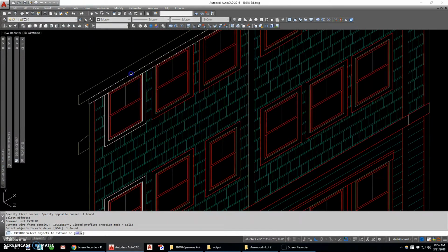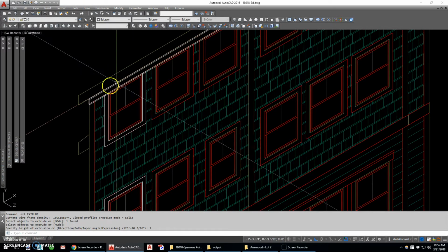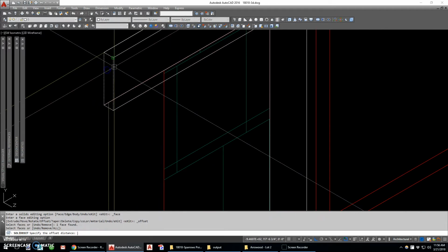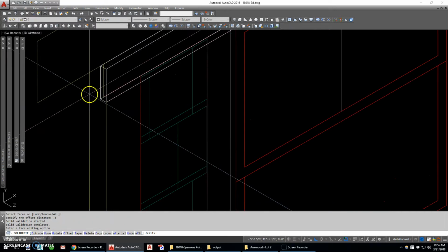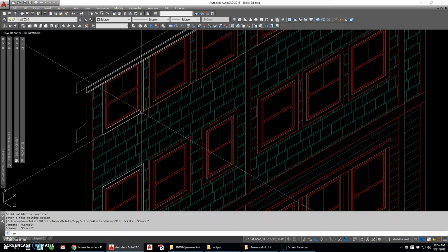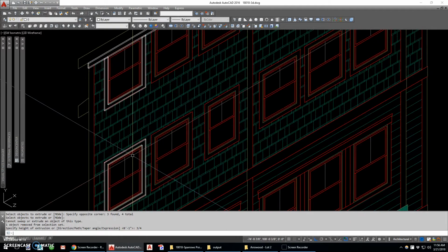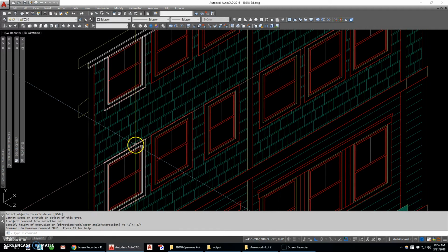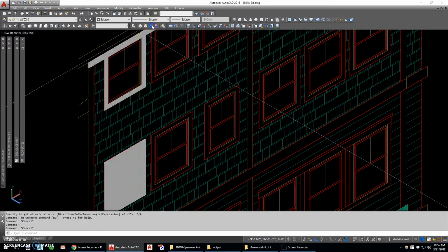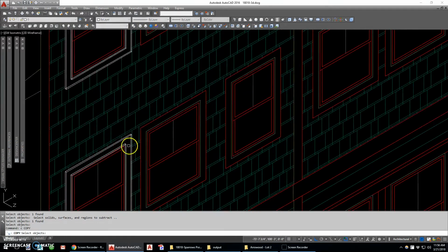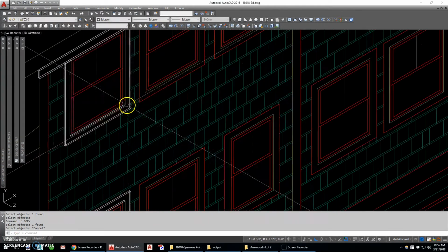So what I'm going to do here is extrude this top piece 1 inch. And while I'm remembering, I'm going to actually offset that face another ½ inch. So it's an inch projected on the side as well. And I'm going to extrude these things 3/4 inch. I've got to subtract. This is a good object, but the lower one I need to subtract out the center. Now I'm going to copy these.